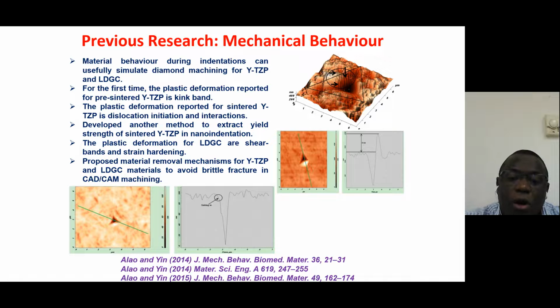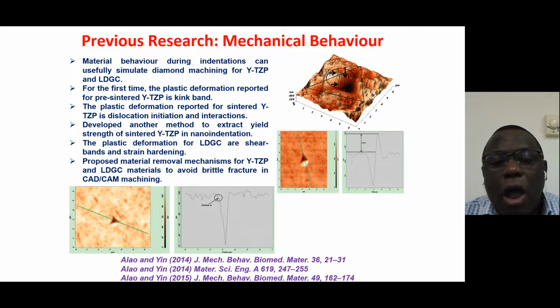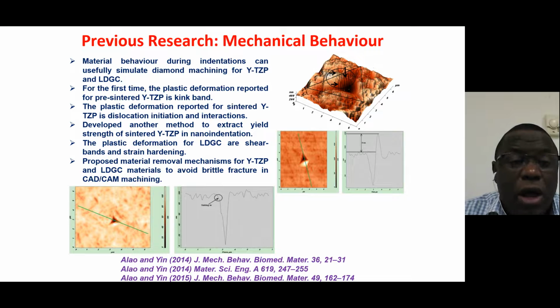Also, when fracture occurs during indentation, that fracture can be likened to the occurrence of fracture in machining or other manufacturing processes. So based on this principle, mechanical material behavior during indentation can usefully simulate diamond machining for the zirconia and lithium disilicate glass ceramics that I considered in this research.